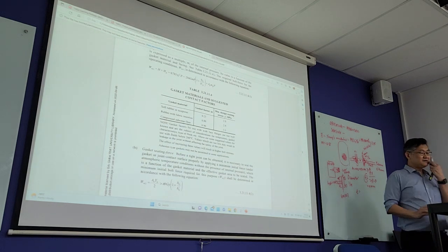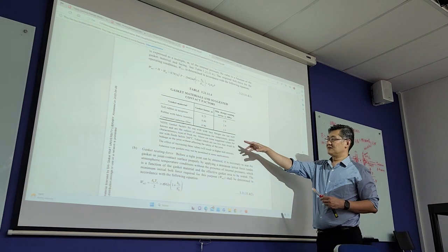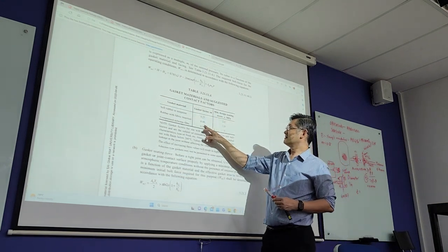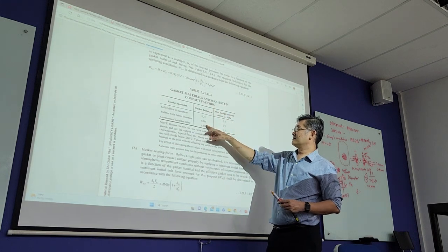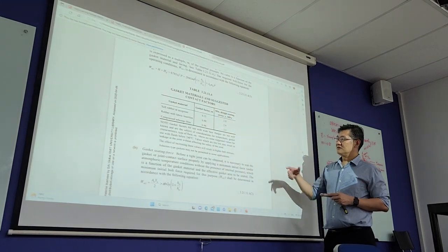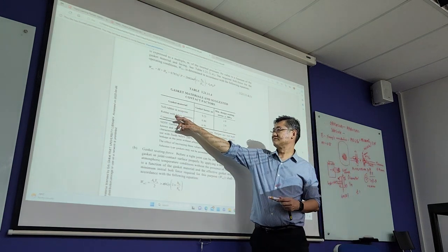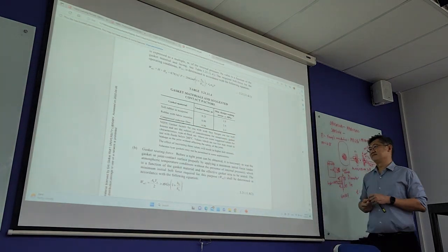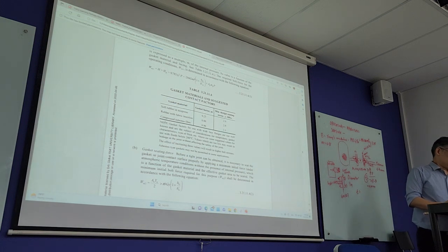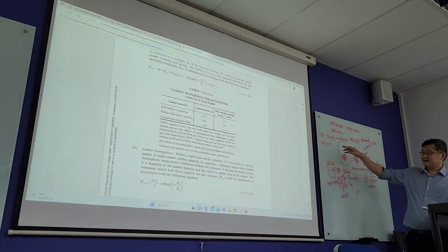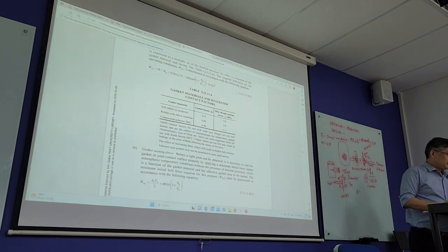Okay, so here is why I use 0.8 as this factor. The gasket material and suggested contact factor is 0.8, because we use rubber for this part. So by using this formula,